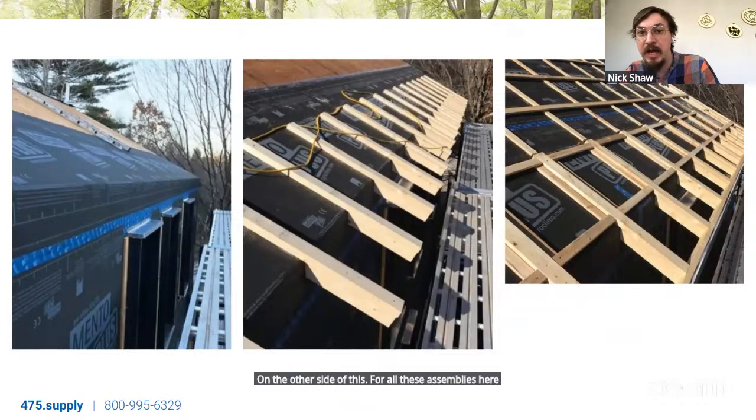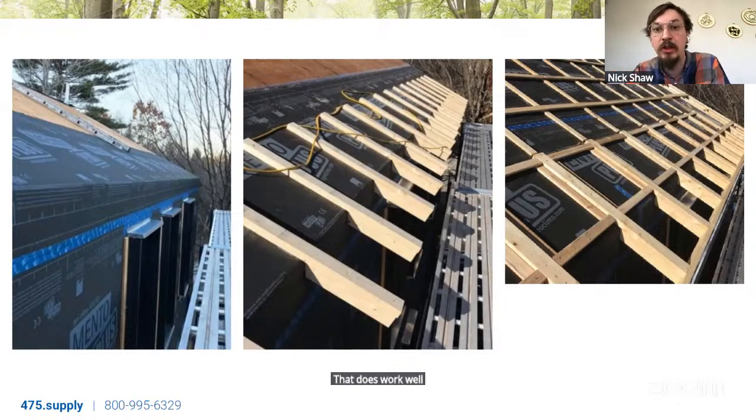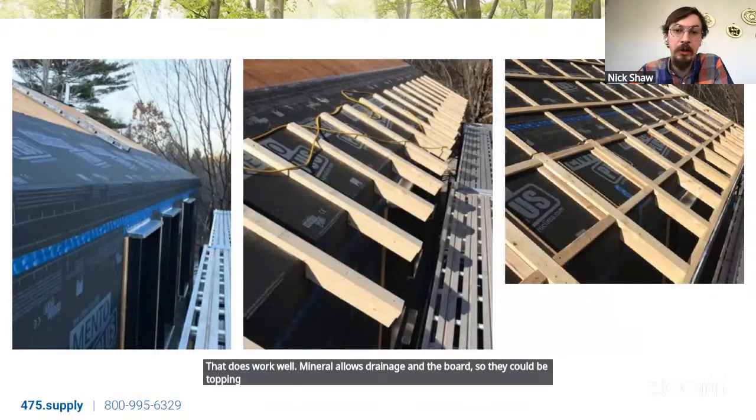I have seen this type of applied roof assembly done with exterior mineral wool. That does work well. Mineral wool allows drainage in the boards, so they could be topping this with exterior fibrous insulation such as mineral wool.